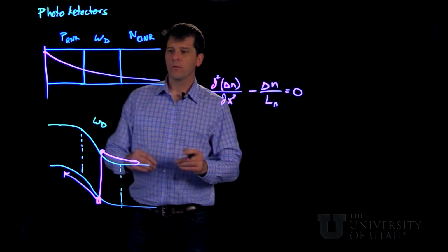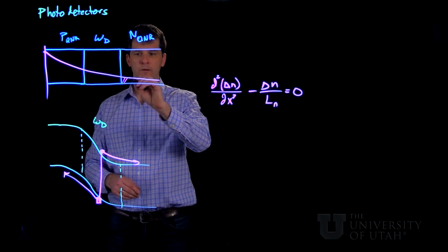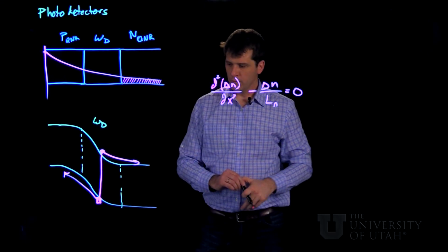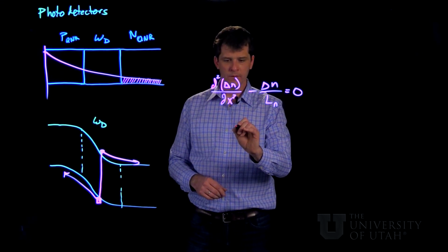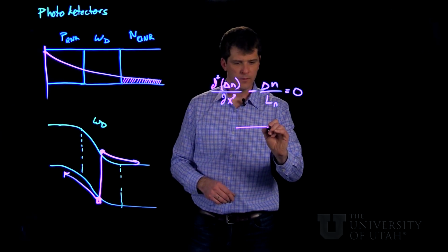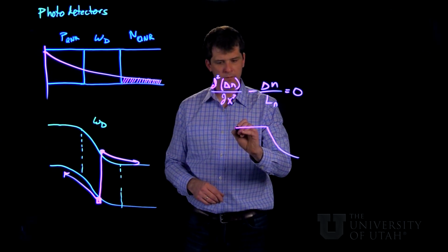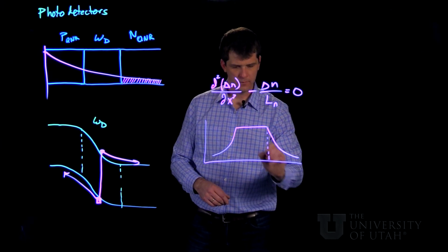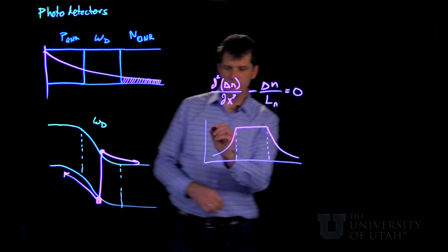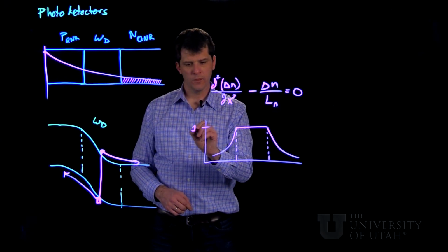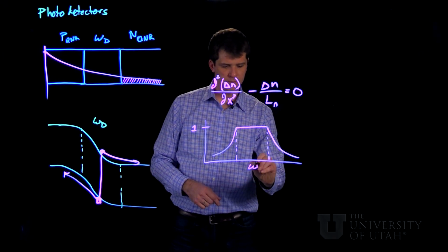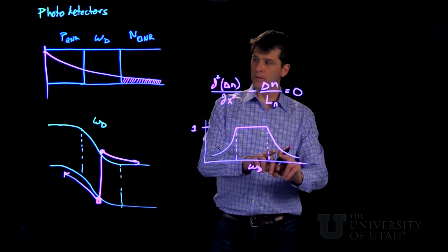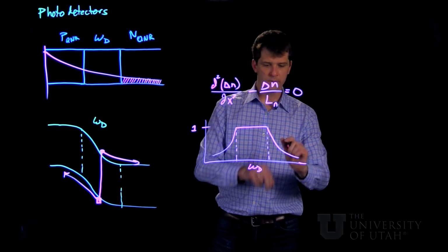But in this case, what we're going to use as the source of this current is that fraction of light which comes here. So a nice way to look at this is to create a function which tells you how much photocurrent will be collected, or a collection efficiency function. So if we have this at 1 or 100% collection, representing the depletion width, we can then look at the collection efficiency in both of the quasi-neutral regions.